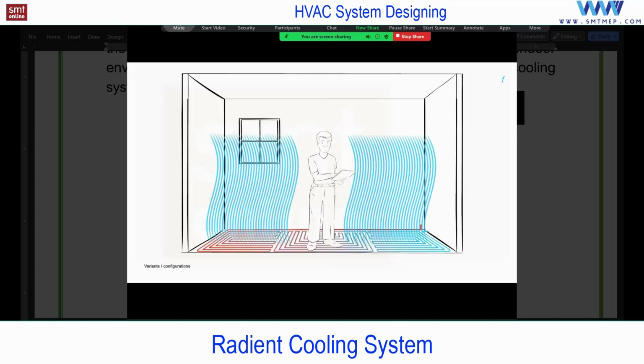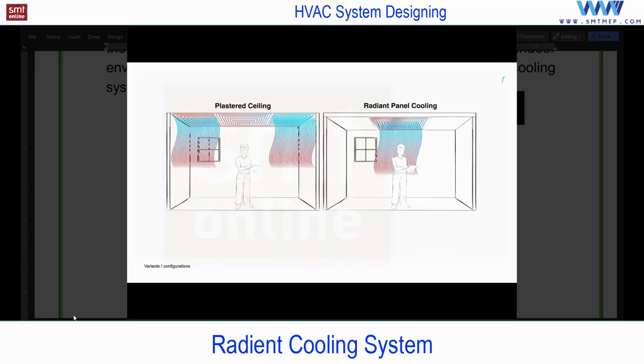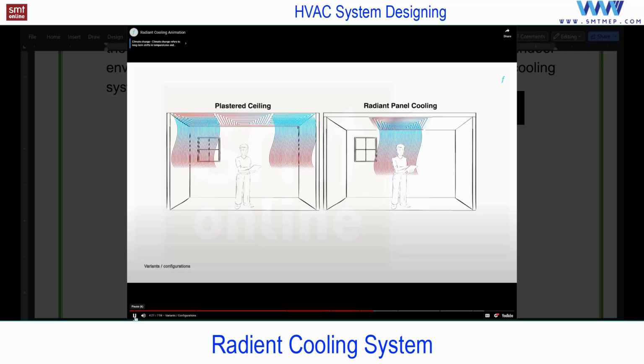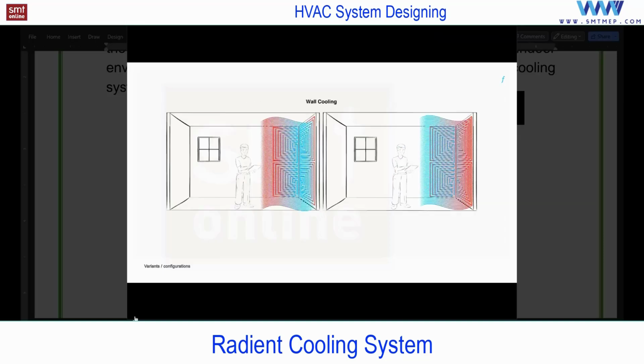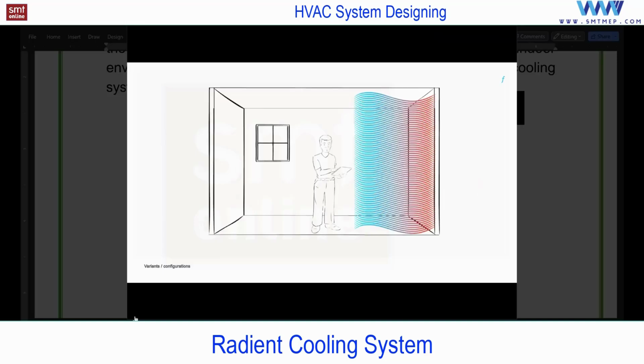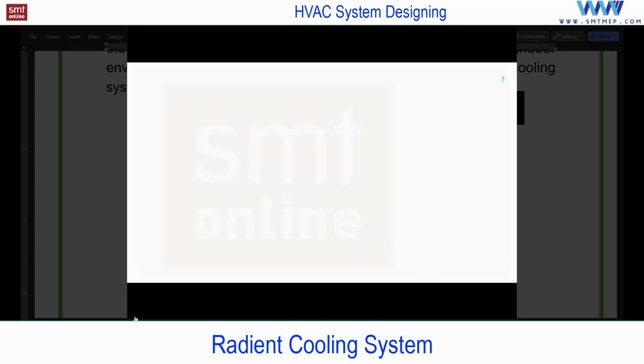Radiant floor cooling. As the name suggests, pipes embedded under the floor cool the space above in this layout. Radiant ceiling cooling. Installed directly below a structural ceiling, panels with embedded pipes or pipes attached to the ceiling and covered with plaster. Radiant wall cooling. Small diameter pipes are attached to walls, then plastered over, or panels with embedded pipes are mounted on the walls to achieve radiant wall cooling. Pipes may be run from the floor as the same circuit, or a distinct circuit can be installed.